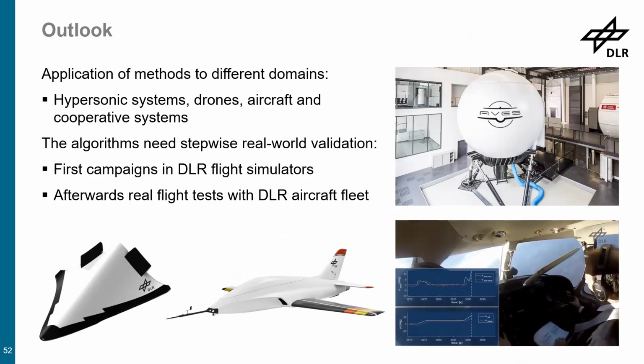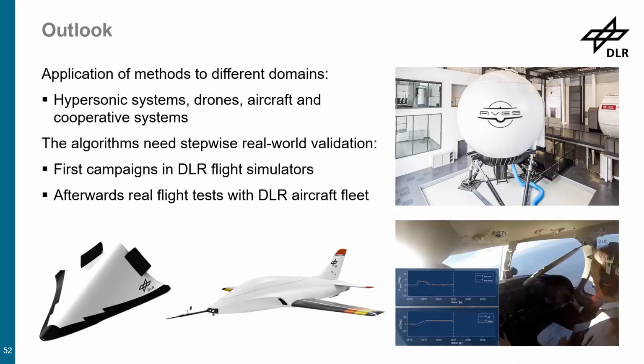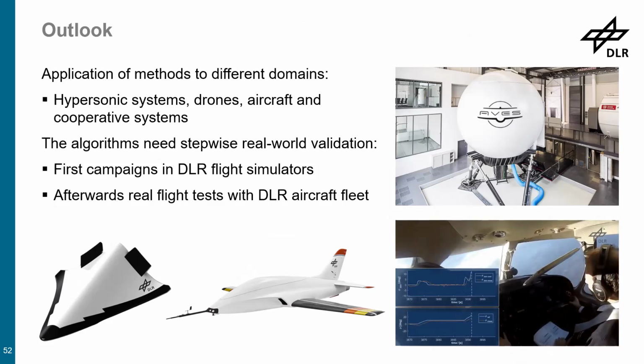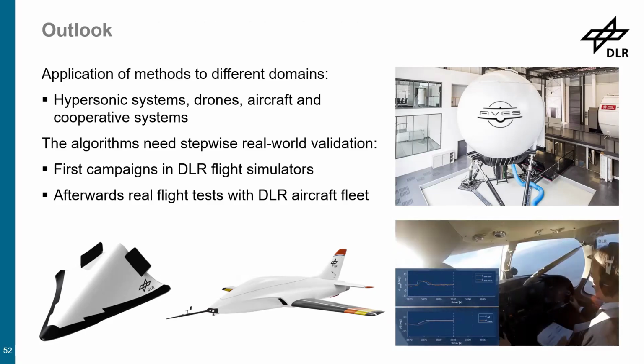You have performance requirements that need to be met, for which we don't yet know how CBFs would interact, right? When you have a pilot in the loop and a safety filter in place as well, what will happen to the handling qualities when the safety constraints become active, right? Still an open question. Maybe we can investigate this in the simulator, or we also have aircraft that can be used to do so.